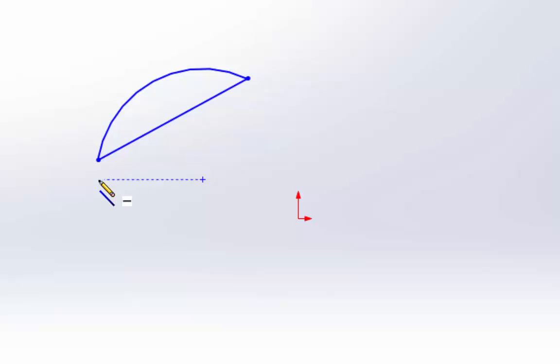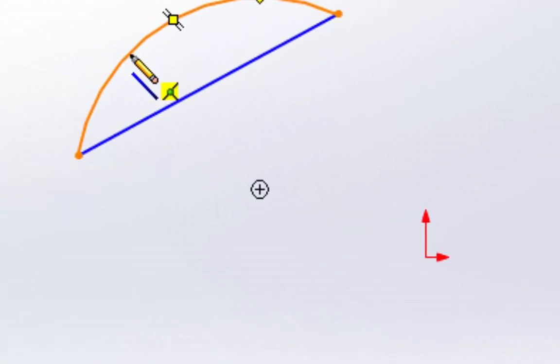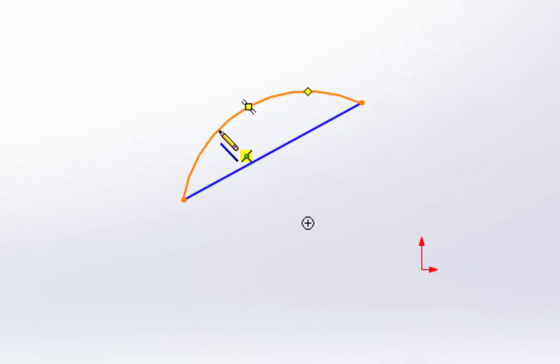And if I start bringing this to, say, the arc, what you see is a few different things. You see the crosshair, which denotes center. So if I needed to get that, I'd be able to find that right there. There's this yellow dot with two bisecting lines. This is the midpoint of the arc, and actually, as you see, if I come over it, in the yellow box right next to my mouse, you can see that's the midpoint relation.